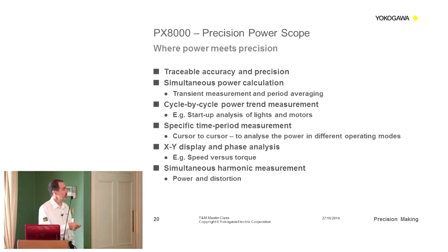So that means that we can do cycle by cycle and choose which part of your waveforms you measure the power. So if you've got varying power, for instance, a process, I've mentioned a printer, for instance, or even a microwave, which basically has power on, power off periods, you can bring up your cursors and measure power of particular parts. And of course, this is something you can't do with a traditional averaging type power meter.